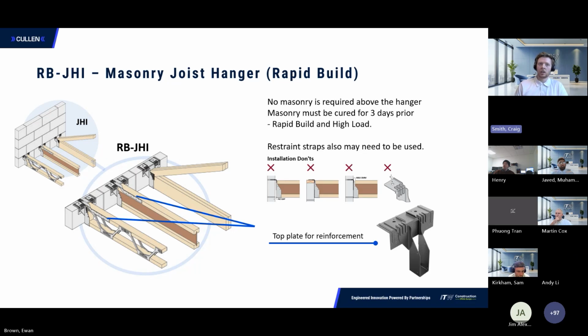You do have the option to add more blockwork, and this will increase the load capacity. So we have 2 load capacities for this, one with blockwork above and one without blockwork. This is in our technical guide, so you can see those. So it's very important to be careful what you're specifying. Some of the benefits of not needing that blockwork above is that you can build a bit faster. Your internal walls and the next story of blockwork can be built sooner, and it reduces some working at height risks that can be involved.